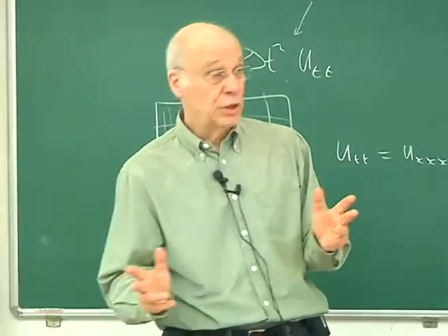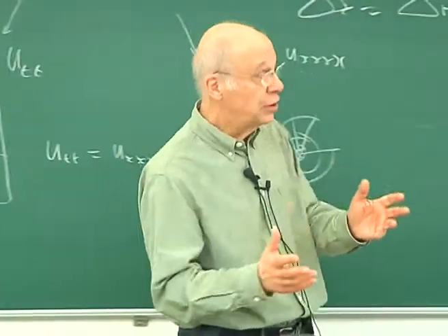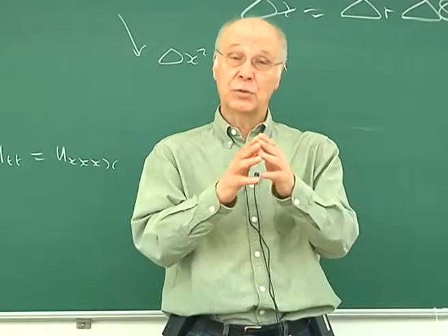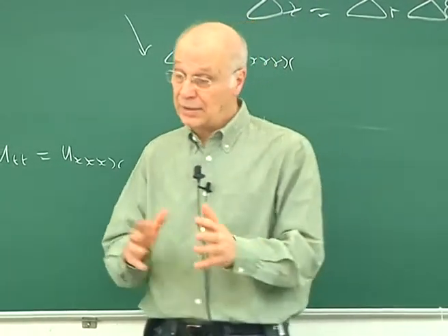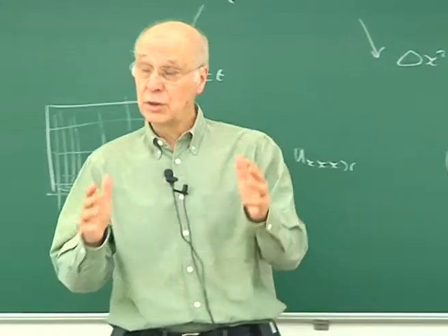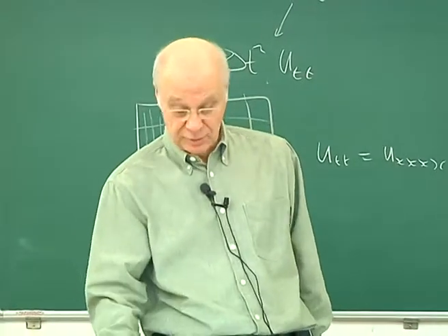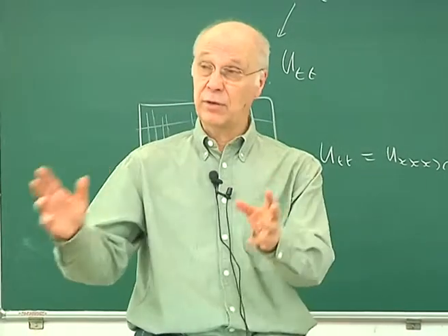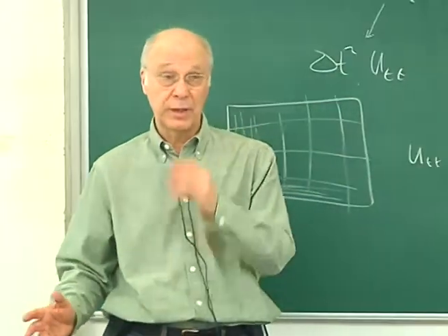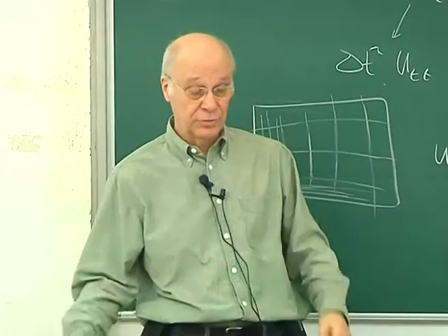And to do that, you need two ideas. You need a formulation of the governing equations, which is called a conservative formulation, and then you need to apply it to volumes of fluid. That's finite volumes of fluid. Then there is a whole area of numerical methods called volume of fluid, which adds certain extra things to do with free surfaces.